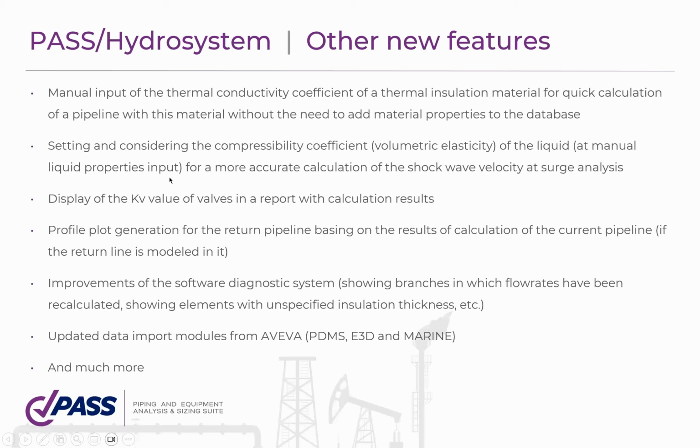Also, in the newest version of HYDROSYSTEM, we've added display of the kV value for valves in the report with calculation results. We upgraded our profile plot generation. Now it's capable of automatically generating a plot for the return pipeline based on the results of calculation of the current pipeline, if this return piping system is presented in the piping model.